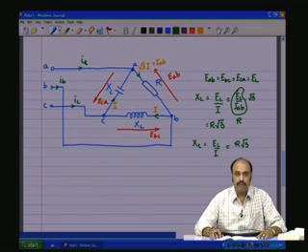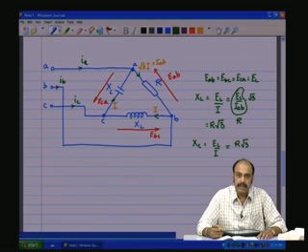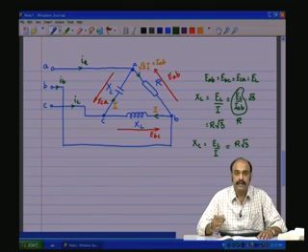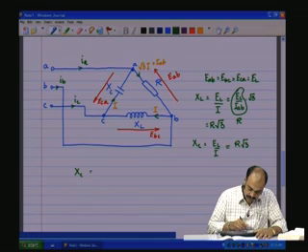meaning you have the same effective value of currents flowing through all the 3 lines displaced 120 degrees apart, you now add 2 reactances, one XL, that is the inductive reactance, and XC, the capacitive reactance, as shown, such that XL value will be equal to XL equal to XC equal to the resistive load into root 3.